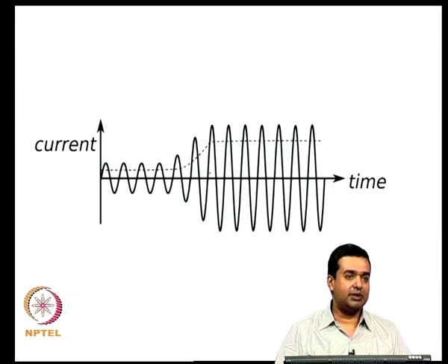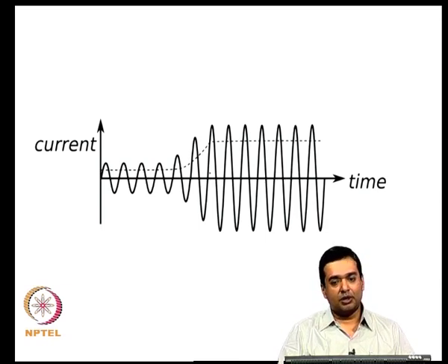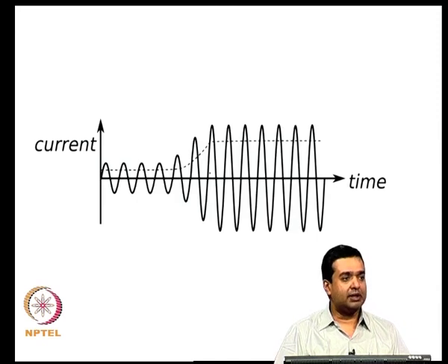So, you are talking about 10 milliseconds, 20 milliseconds going up to maybe 100 milliseconds, and it is not the instantaneous time that the students in power electronics are typically looking at, where for a power semiconductor device you are talking about switches that can operate in microseconds or in tens of nanoseconds. So, the instantaneous from the power electronics perspective and the instantaneous from the power systems perspective, one has to keep the appropriate time frame in mind when you are looking at how these systems respond.